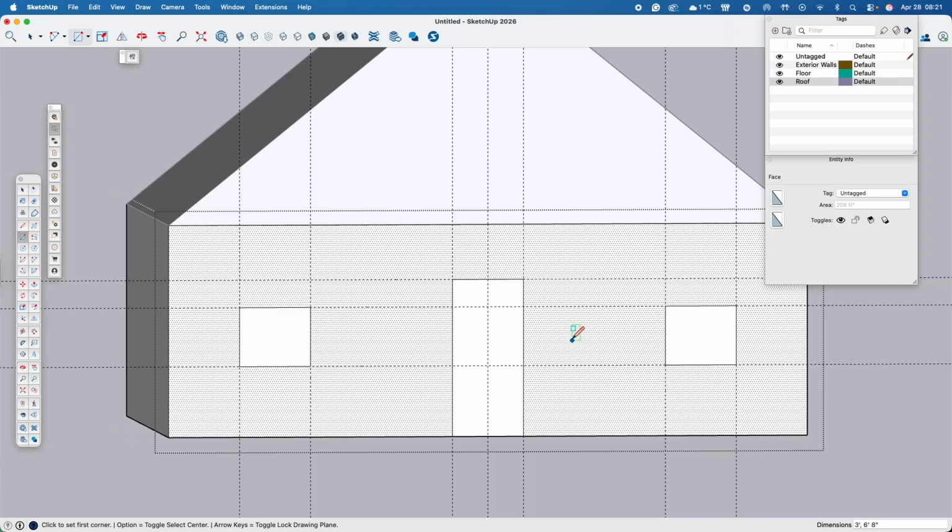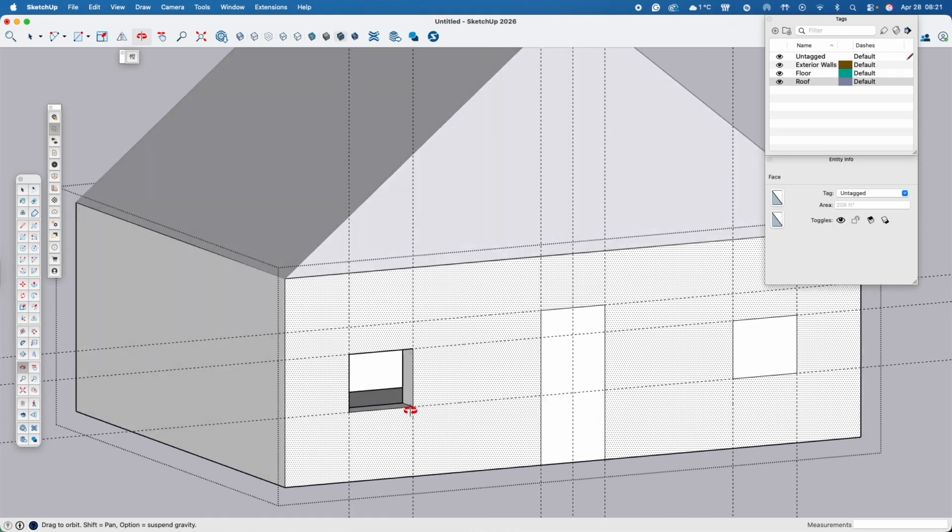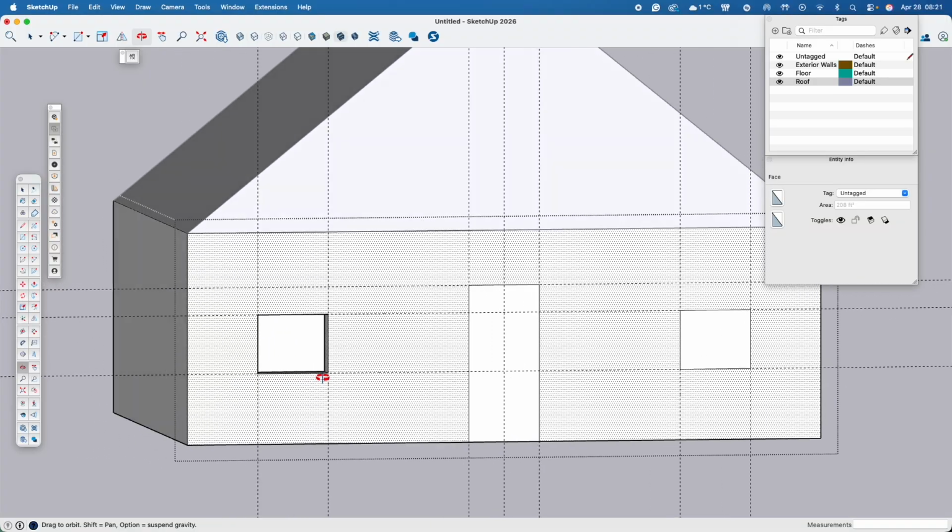that's white, that's dotted. I want to change that because I'm going to work now on that, and I'm going to open the windows, literally. So spacebar for the select tool. I'm still working within my group, very important. And I will click on my window. When I'm here, I'm going to grab the push-pull tool, so P on my keyboard, and then I'm going to move that wall until it says on face. And then I'm going to click, and that will have opened my window.